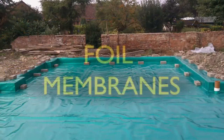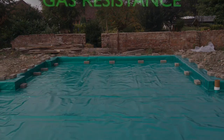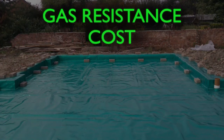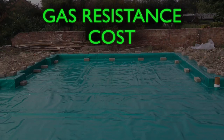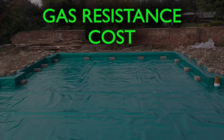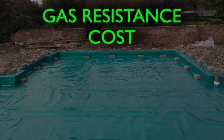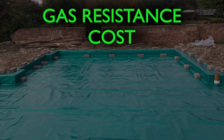Foil-based membranes. Adding a foil core to LDPE or HDPE membranes dramatically increases the gas and vapour resistance of the membrane without a corresponding dramatic increase in cost. This makes them a good option where elevated risks are present and it's not feasible or desirable to use source remediation to lower the concentrations present. There is a common misconception that because the membrane has an aluminium foil in its build-up, that this will offer good all-round protection from contaminants. While that may be true when considering ground gases, there are problems with this assumption, particularly when VOCs are involved.